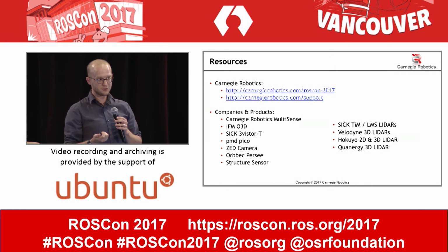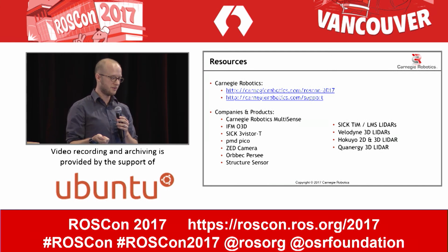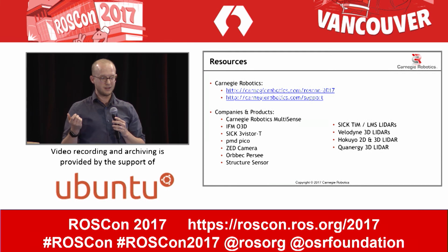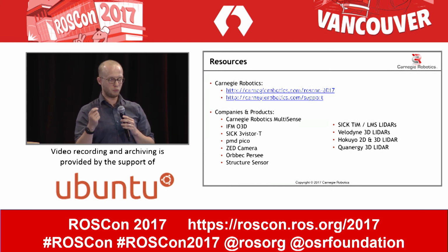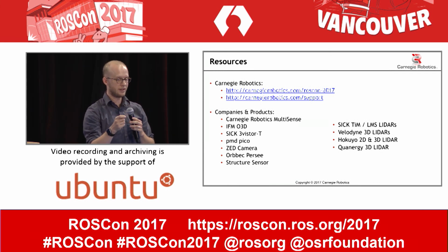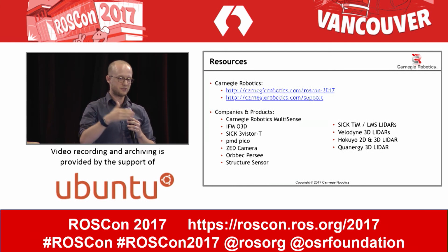And in terms of the materials that you should use, you need something that has visual texture for the stereo to work off of, and you want something that doesn't cause distortion to the laser data. So checkerboards are great for calibrating camera data, but in most laser data that we've looked at, you actually see the checkerboard in the laser data. The white and the black appear to be different distances away. So when you're doing these laser to stereo calibrations, it's important to pick materials that don't have as much visual contrast between them, and then you aren't introducing that sort of range error in your LiDAR data.